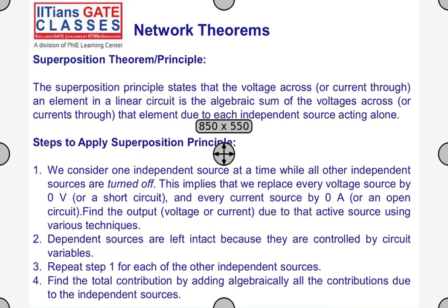You cannot apply it for powers. Power is not a linear quantity. This is important. Don't apply the superposition theorem whenever I say find the power. Power is not linear.